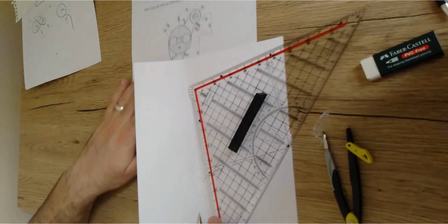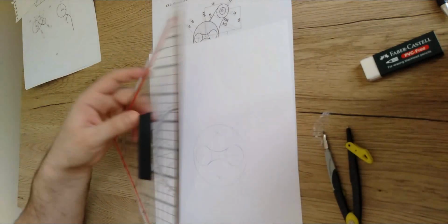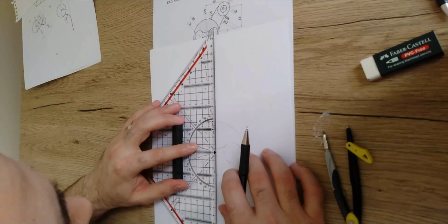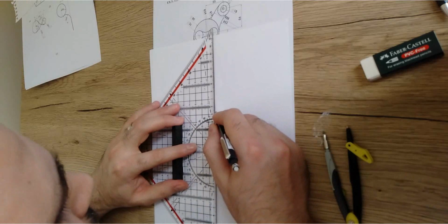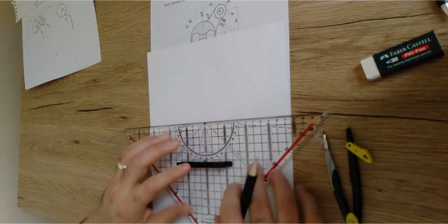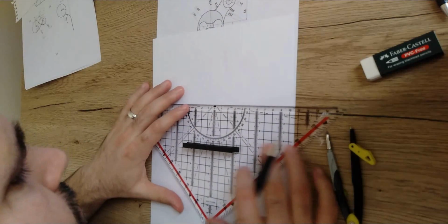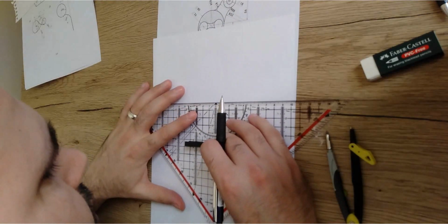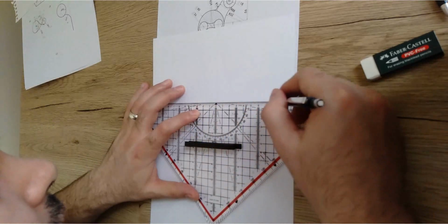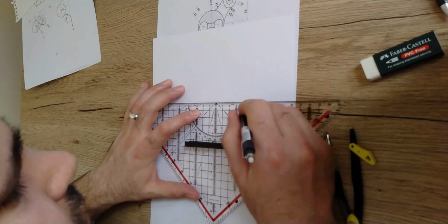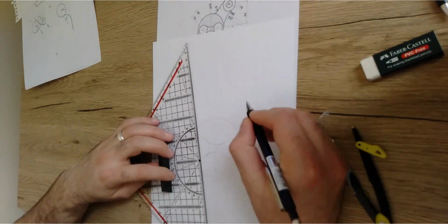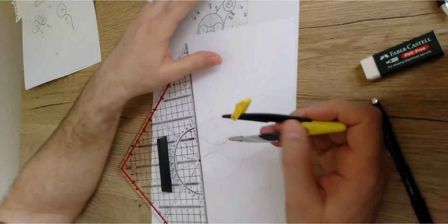Let me put this one down. So just measure 56 over the vertical line. Then from this point, I'm just going to draw a very light line that is going to be the locus to the center that I'm seeking, which is the center of the two circles. Just a very light line. Over this line, measure 55 millimeter and mark a point. This is going to give us the center of these two circles. Then I'm just going to draw the two circles.